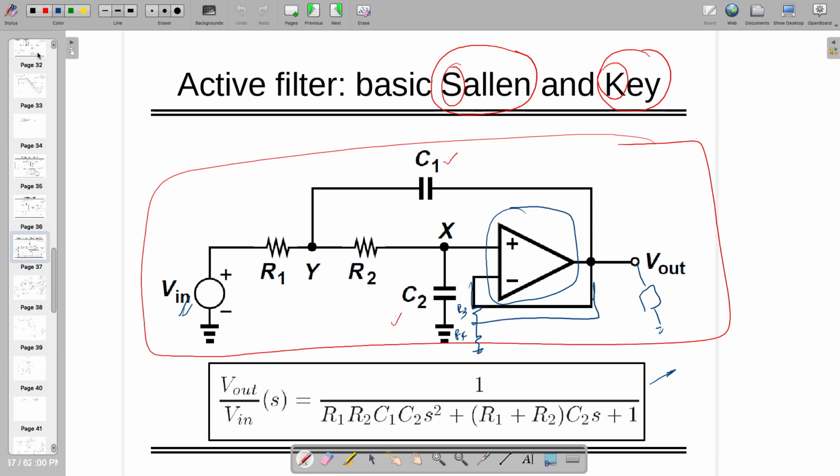So at the end, the transfer function which we are seeing does not depend on the internal structure of your op amp, but the op amp makes sure that this transfer function will be PVT independent, so for any process, any voltage or any temperature, it should not change. You understand, Divanshu? That's the main crux of the story.